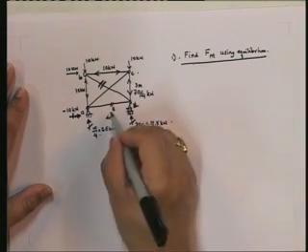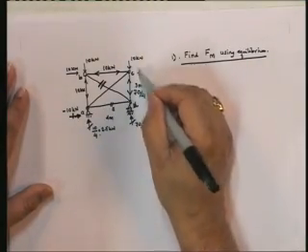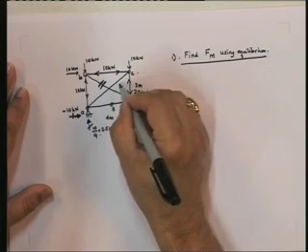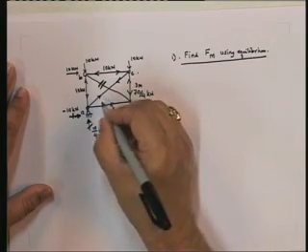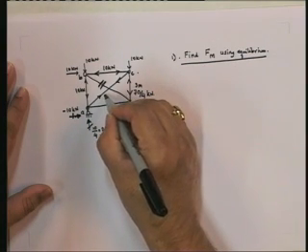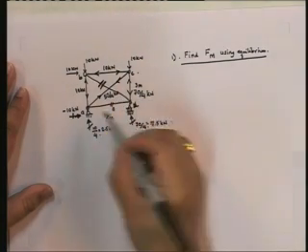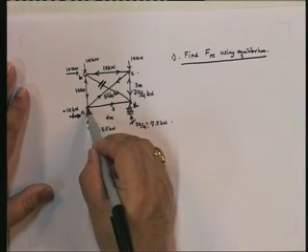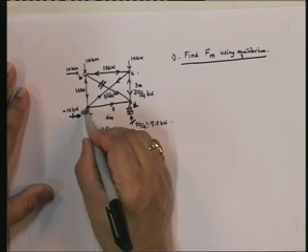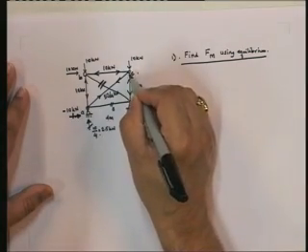So compressive force, this is 0, and from that, if you go about it, you will see that this becomes 30 by 4 and 40 by 4, and so this is equal to a tension force of 50 by 4 kilonewtons. And now you will see that the equilibrium of this joint is satisfied automatically, and the vertical of this is satisfied as well.